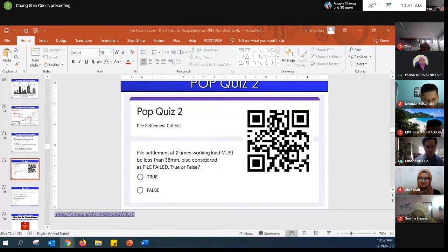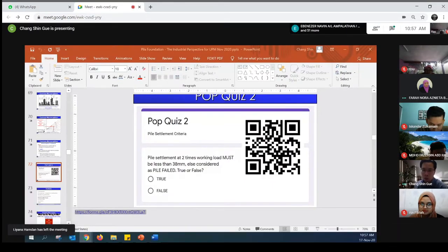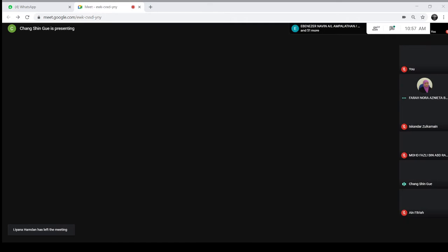Okay, that's a good question. Typically for an SI, the number of boreholes depends on the areas that you're dealing with. In terms of buildings, for a small, let's say one block building, you may have 5 to 6 boreholes. But it actually depends on the soil condition.